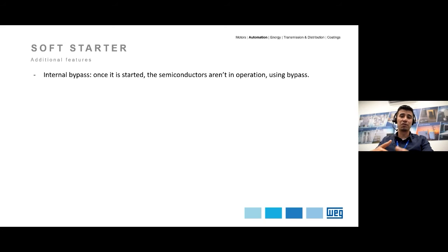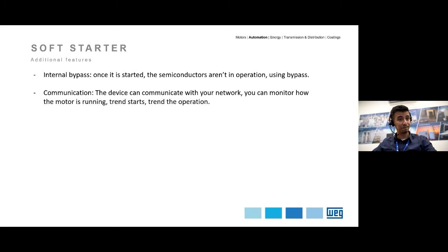And also in terms of reliability of the system itself, it's better to keep the bypass, because its withstand to voltage fluctuations is better as well. Okay, so that's a very good feature we have on the SSW 900.